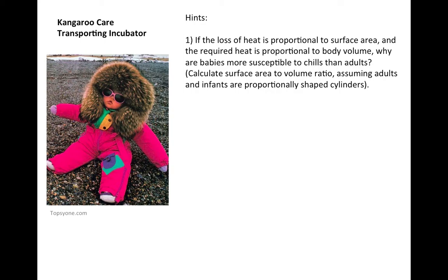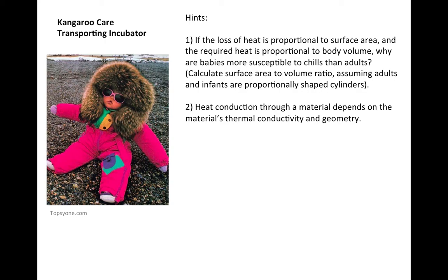And that scales with size. And so the baby is more likely to lose heat through that surface area in proportion to its body volume. Heat conduction through a material depends on the material's thermal conductivity and geometry, and that can be captured in this equation. The heat is equal to a material property, the thermal conductivity, times the area of the interface between that material and the inside and the outside, divided by the length or the thickness of the wall between the inside